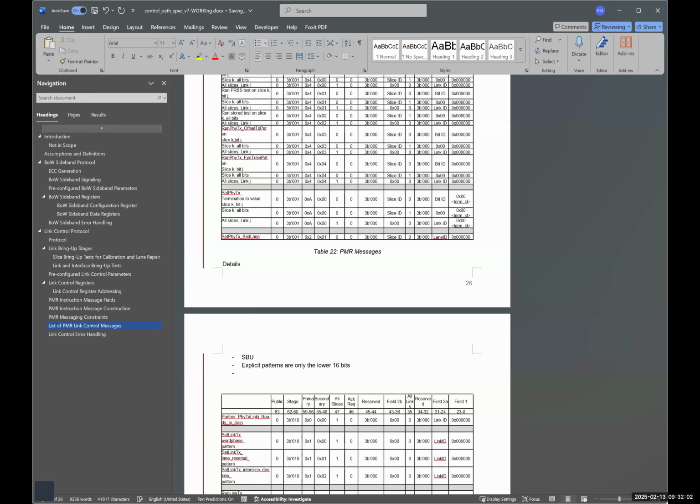So are these IDs implementation dependent then? Do they refer to specific voltages that are preset? Correct. When the TX calibration happens, it determines certain programming values that are required to terminate the link at 150 ohms versus 50 ohms. So it is supposed to store those values. Then the RX can request one of the two terminations when it is doing VREF calibration on its side. So once it requests a certain termination, I think the ID will probably need to say what we are requesting: a 50 ohm termination or a 150 ohm termination.